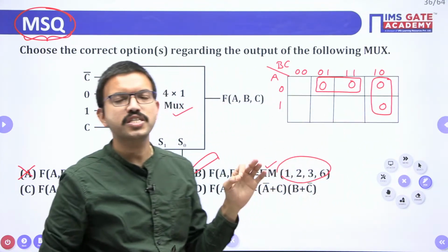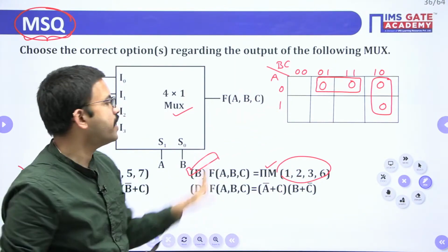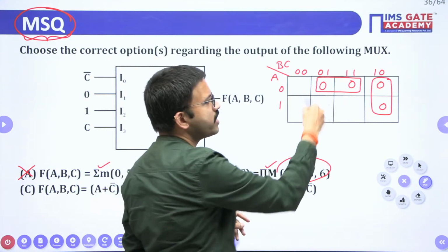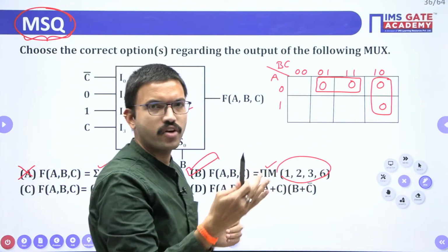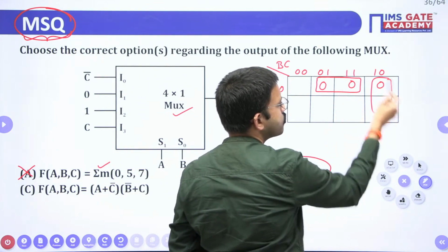Whenever the question is regarding prime implicants or essential ones, you do all possible groupings. But whenever the question is regarding the minimized function, you do only the required groupings. Unnecessary groupings you can avoid. With practice, you will come to know you need not group these 2 zeros.